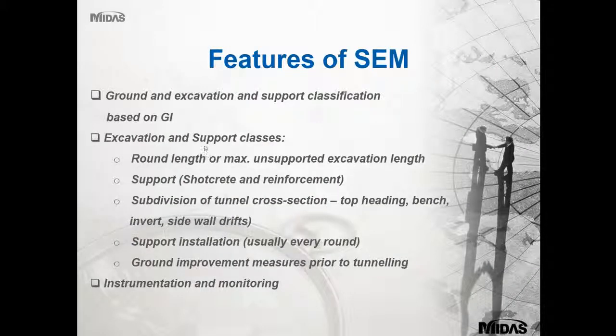So just the SEM, the excavation drift cross-section for excavation. The time and duration at which supports are installed depends on the ground geology. For a good quality ground, the maximum unsupported excavation length tends to be much higher than what is allowed for in the SCL method.